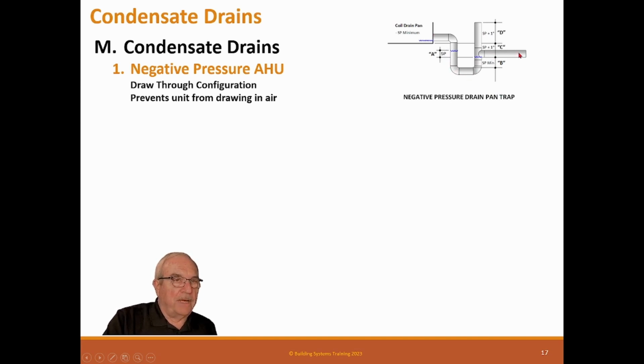If you fill up the pipe, this will become vapor locked. So basically, without this vent here, this has to be the vent. So it has to be running probably less than a quarter full. So it needs to be a big condensate drain for that to work. Normally this vent is here to vent this drain, not to vent the trap, to vent the drain. So a lot of people put a solid cap on here. Totally defeats its purpose. I have no idea what's on their mind.